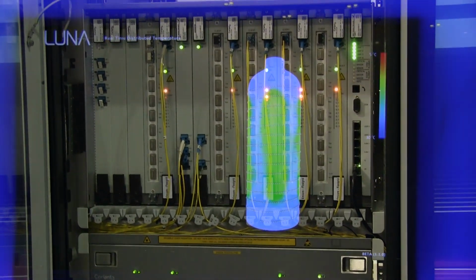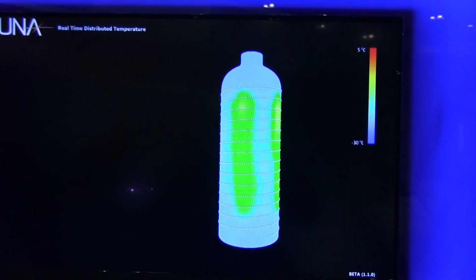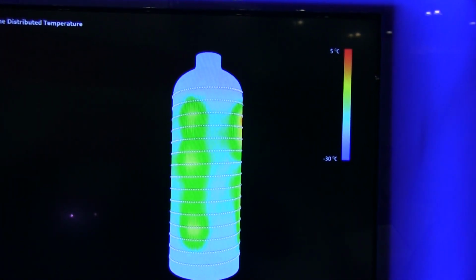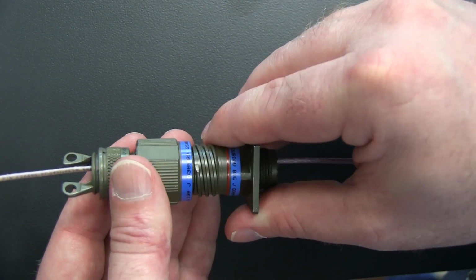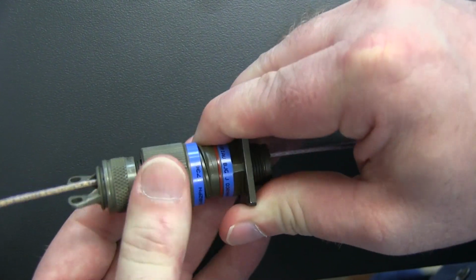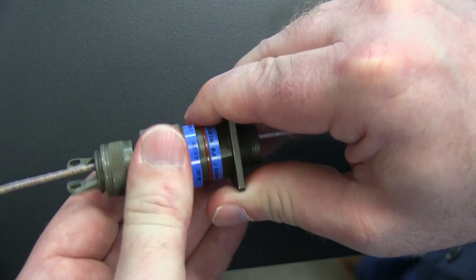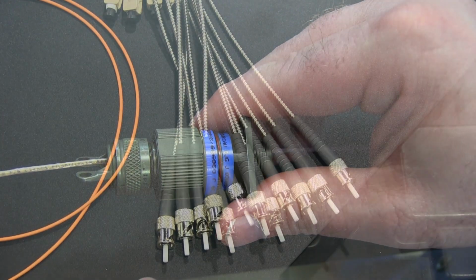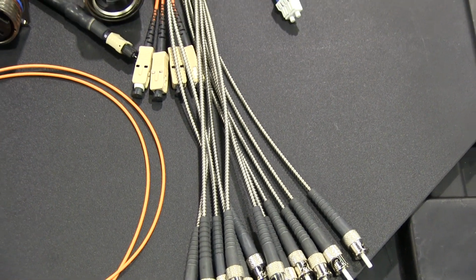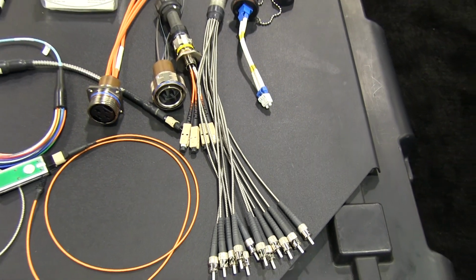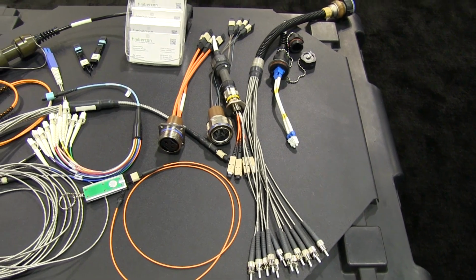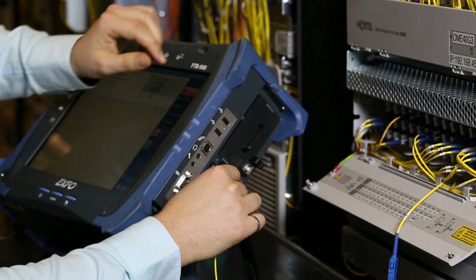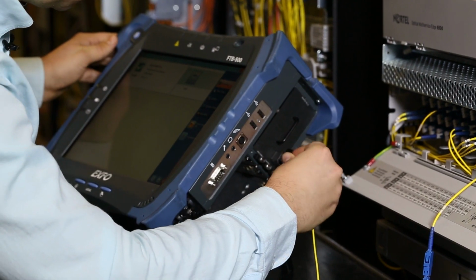Analog signals, such as those in sensor systems, can be more sensitive to signal degradation than the more forgiving digital systems. Some of the most common problems, as well as some of the most vexing, can occur in optical connectors. These can be mechanical issues with fiber, ferrules, or termini, or procedural issues such as contamination and poor handling methods. How, then, does one proceed to isolate and resolve some of the more mysterious system problems that may appear?